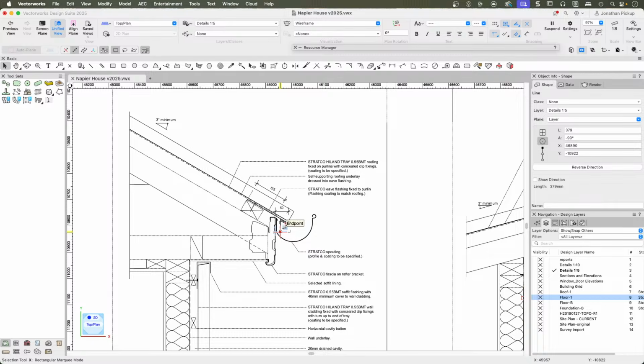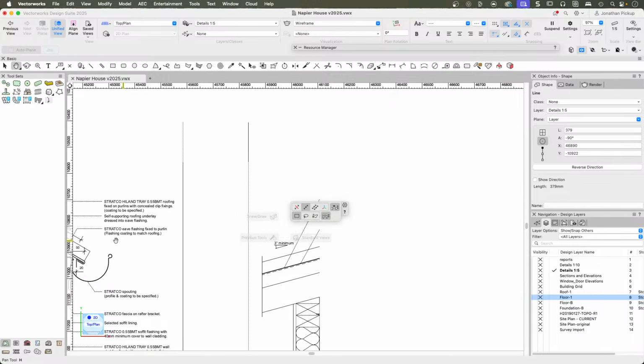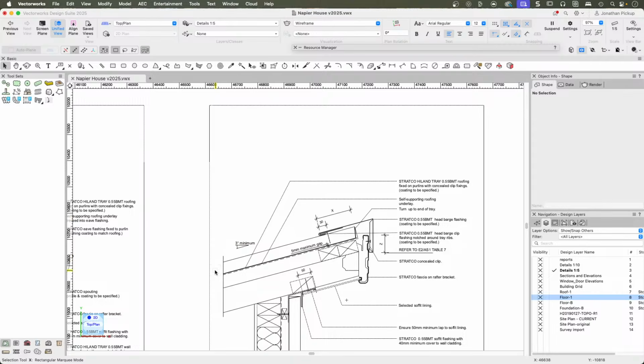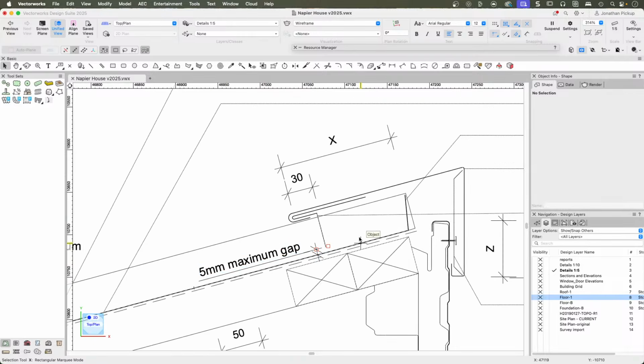Now, that's the 4 Ds of detail. Really important, these 4 Ds of detailing. But there's also 5 physics principles that we have to be aware of when we detail. And the 5 physics principles are kinetic energy. So for example, in this case here, where I live, the wind will blow the water uphill. It'll actually blow the water uphill here and try and get it into the building. That's kinetic energy.